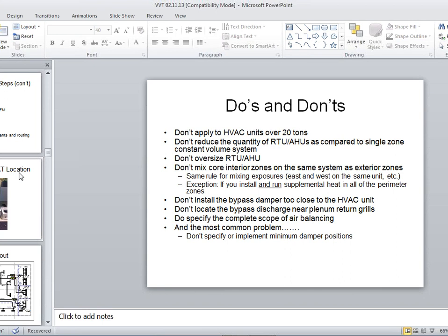If you could retrofit an existing system where you have the ability to modulate cooling and modulate heating, then you could get into some sort of energy savings where you are modulating with a VFD and doing VVT with the VFD. On that previous example that we just looked at, those four air handlers that we were controlling were actually multi-zone systems that we retrofitted with VVT with VFDs. So we were able to save energy where we're modulating the fan down and then also modulating cooling and heat. So that really is the most that you're going to run into.